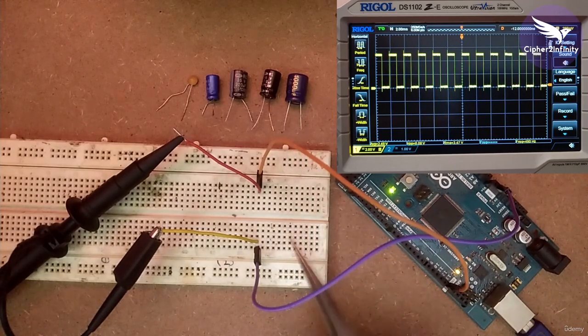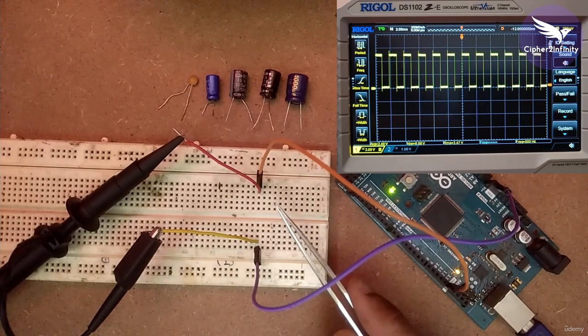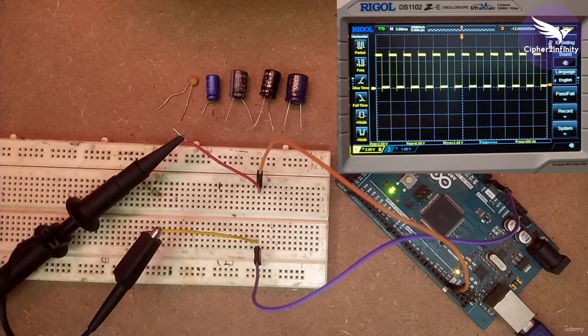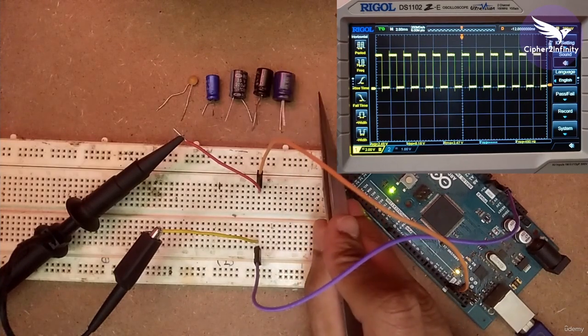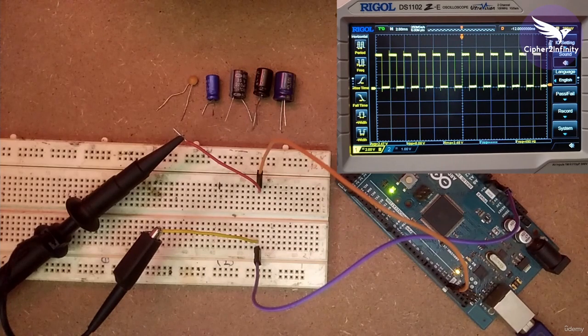And if you have to filter out a higher frequency, for example in megahertz, we discussed in the impedance versus frequency plot that the 100 nanofarad capacitor provides lower impedance at a frequency of 10 megahertz or somewhere around that. So whenever you have to filter out a higher frequency, you will have to go for lower values of capacitor, and whenever you have to filter out a lower frequency, you have to go for higher values of capacitor. This is a very important point, and it gives you an idea what range of capacitor you should choose to filter out a certain frequency.